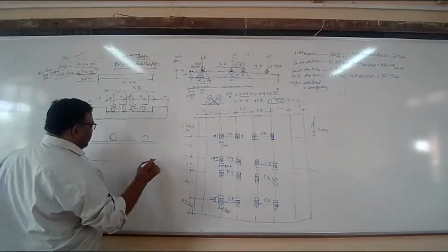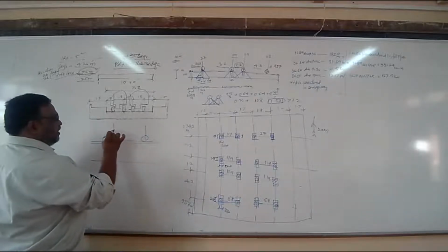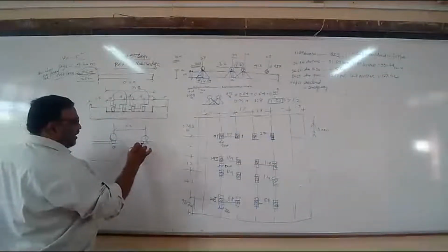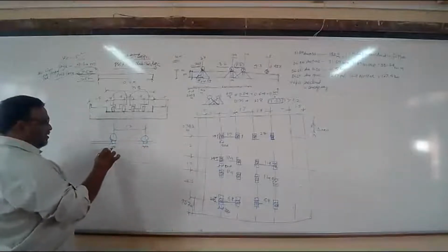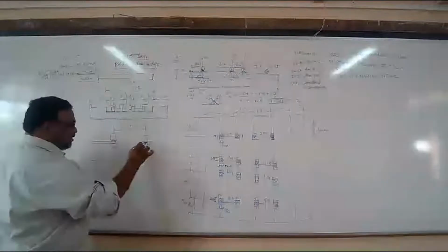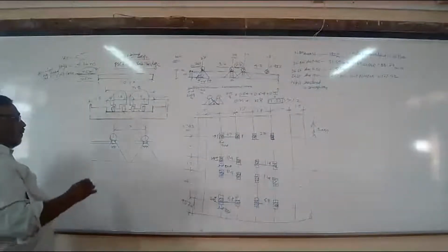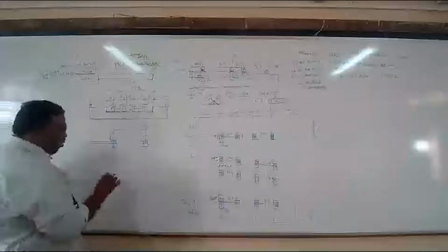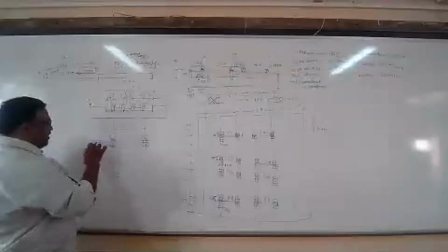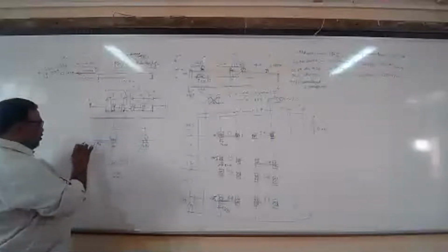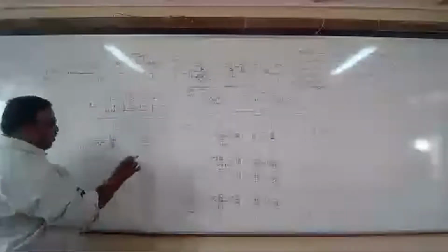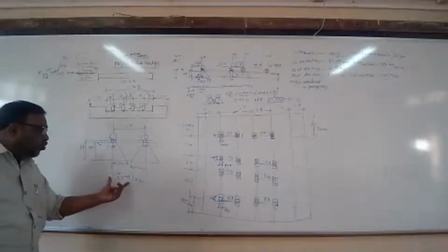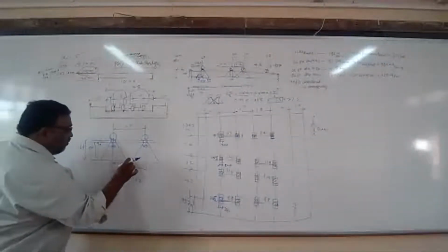This is the deck line. ये सेंटर टू सेंटर डिस्टेंस कितना दिया है, 1.2. यहाँ पर कितना विड्थ कॉन्टैक्ट में है, 250 mm. यहाँ कितना है कॉन्टैक्ट में इन द डायरेक्शन ऑफ मोशन, 250 mm. यहाँ से ऐसे डिस्पर्शन आएगा. अभी देखिए ये सेंटर से सेंटर डिस्टेंस, ये डिस्टेंस कितना रहेगा, 0.25 प्लस ये वेरी इंपॉर्टेंट 90 था प्लस दिस 550, so this overall is equal to 0.64 meter. यहाँ से भी इतना ही रहेगा, this will get multiplied by 2. मैं जस्ट चेक करना चाहता हूँ कि अगर मैं ये दोनों को ऐड करता हूँ तो कितना डिस्टेंस आएगा या दोनों के बीच में कुछ गैप रहेगा क्या?